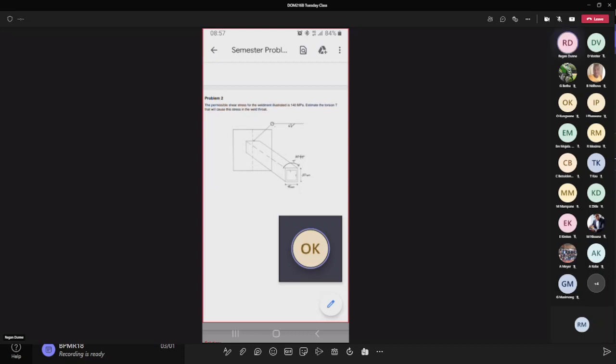Yeah, if we look at, imagine a tire. So your car is sitting off the ground, and all you do is apply a torque. It's only going to turn the tire. It's not going to want to push the tire down or to the right. You have no translational force, what they call transverse force. There's no force acting directly down or directly to the side. So if this thing's in space, all it's going to do is rotate. There's going to be no translation.